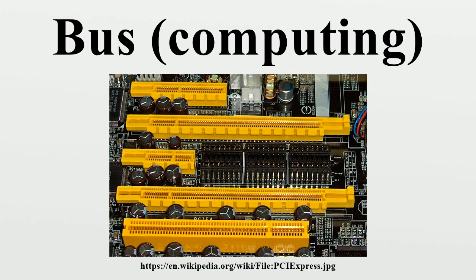They may, as with ARINC 429, be simplex, i.e., have a single source LRI or LRU, or, as with ARINC 629, MIL-STD-1553B, and STANAG 3910, be duplex, allowing all the connected LRIs or LRUs to act at different times as transmitters and receivers of data.